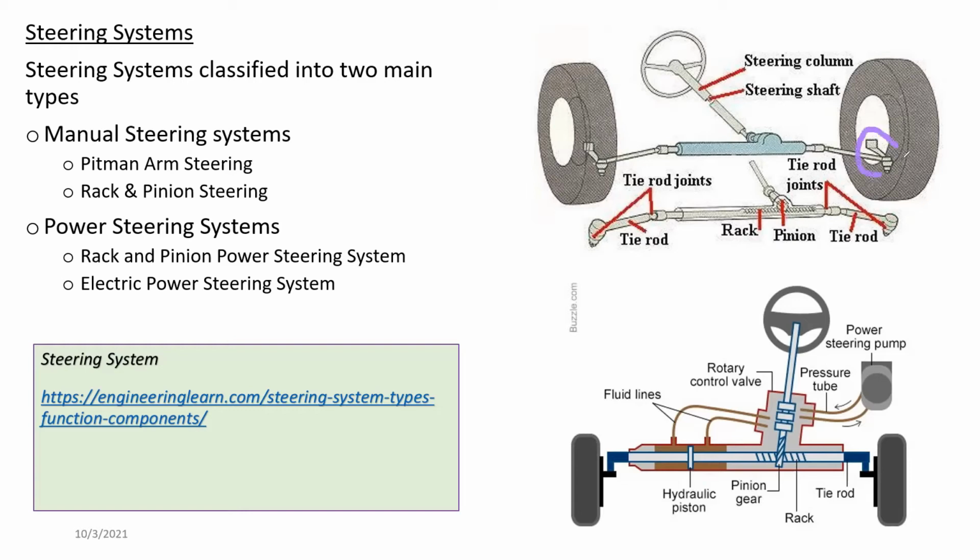Now here, you can see this part. This is where the parallelogram is actually created. This angle, I will show you some photos when it comes to the suspension system. In the front suspension, if you look carefully, there is one single component called the steering knuckle. In the steering knuckle, this part is there. The steered wheel and everything is connected to the steering knuckle.